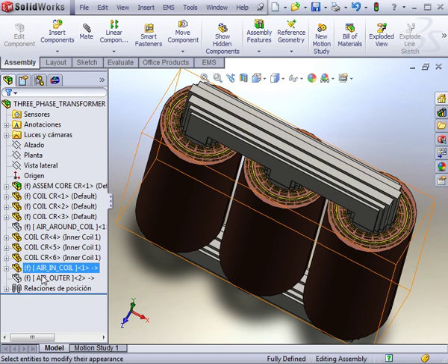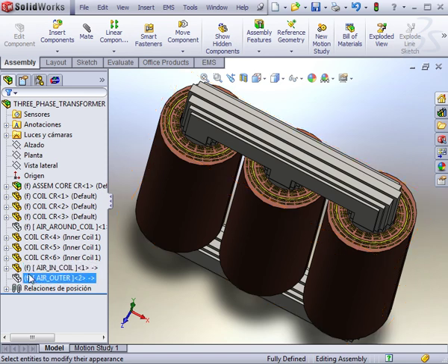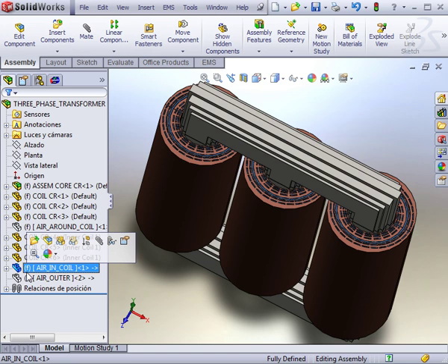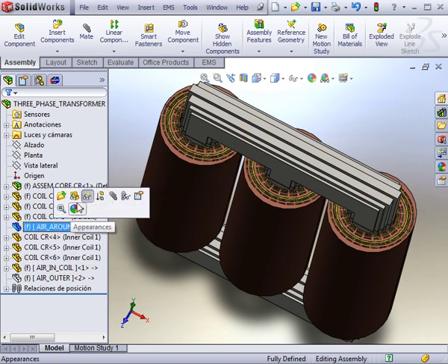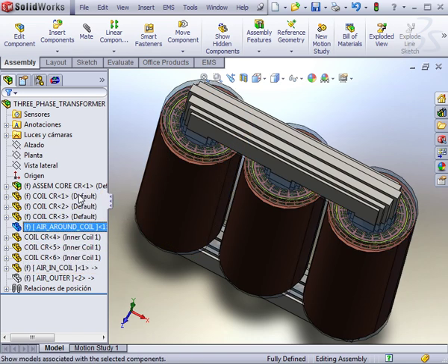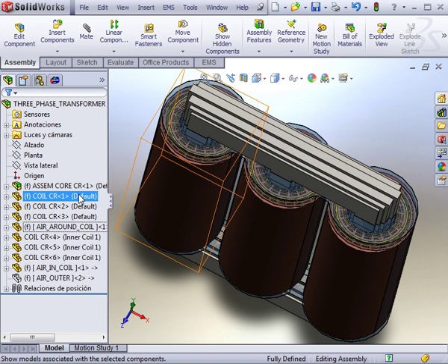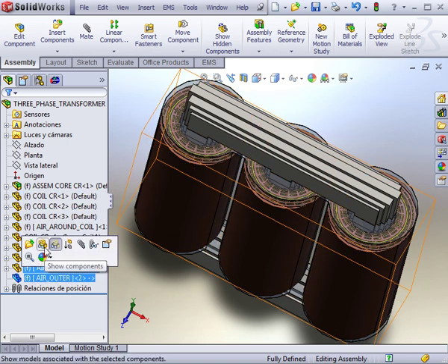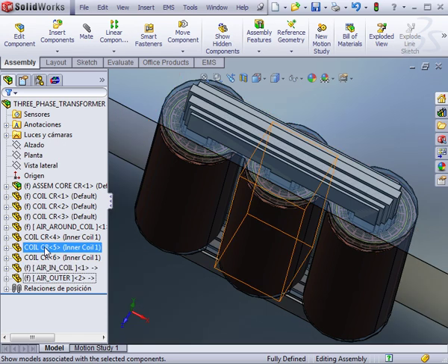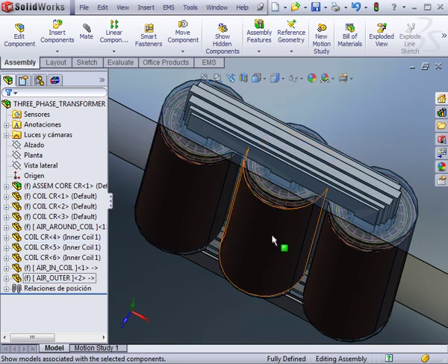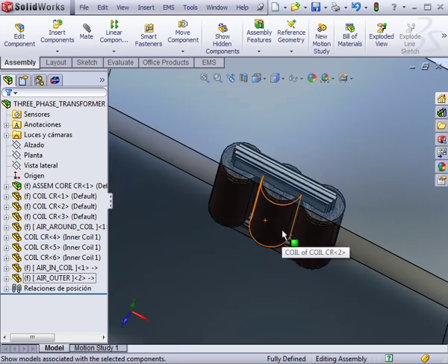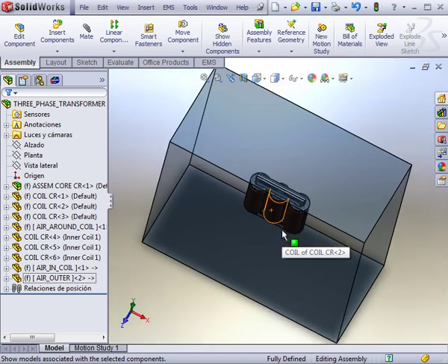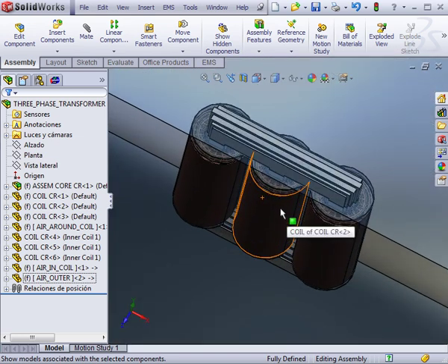Notice that there is another set of parts which represent the air. One part represents the air within the coil. Another is the air directly around the coil and in contact with the core. Fields can be strong there. Therefore, it is essential to add them in order to analyze the fields close to the bodies. They reflect the coupling between the transformer's parts. The outer air is an enclosure volume. This part should be made sufficiently large to ensure that fields are small enough at the far edge.